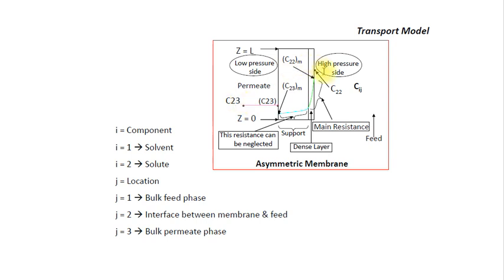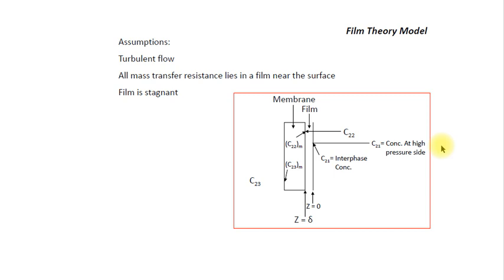and get separated out. The membrane has a higher selectivity towards the water than the salt. So water molecules are selectively absorbed on the surface, then selectively diffuse across the membrane, then dissolve at the other side. The separation occurs due to the different values of absorption coefficient and diffusion coefficient of water and salt in the membrane material. There is one more physical concept applied here, that is the concentration polarization.